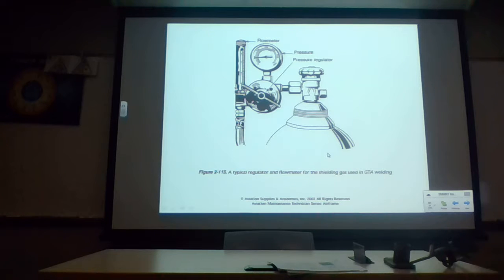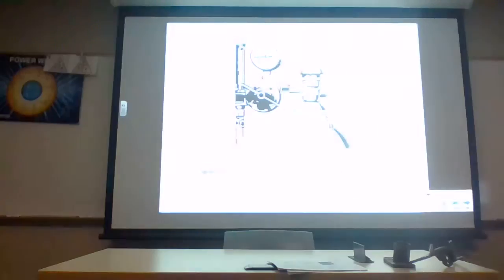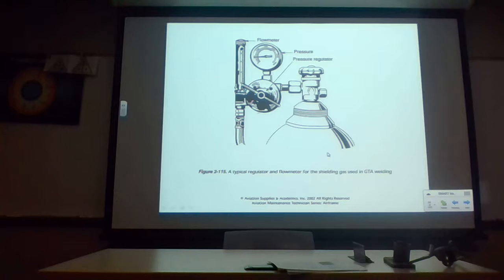So if you're welding maybe in a drafty area, thick. You want to think of it that way. Sometimes helium is used. When you use helium as a shielding gas, the arc is easier to go through. The characteristics of the gas are just thinner. But we do have to regulate the flow of gas anyway.